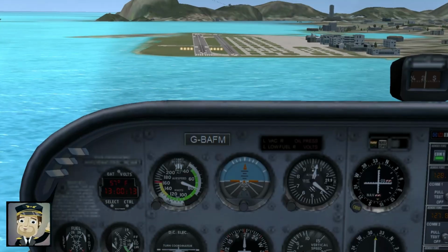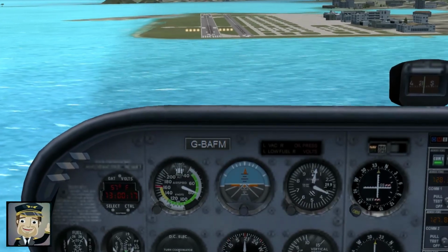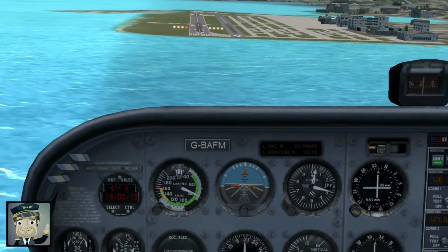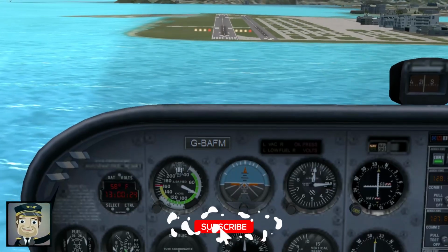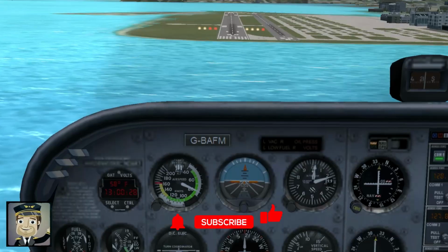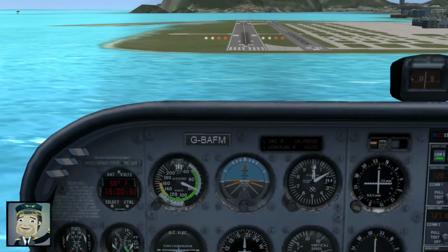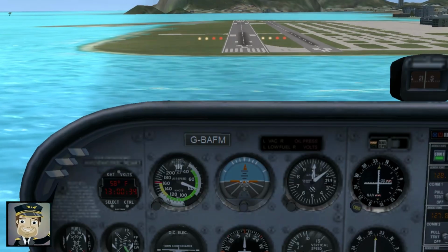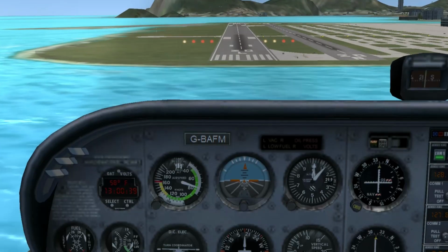During final approach, the pilot's focus narrows dramatically. The outside world becomes secondary. All attention is on the runway picture, descent rate, and the delicate interplay between pitch and power. If anything looks unstable, speed fluctuating, nose wandering, descent becoming erratic, the safest decision is always to go around and re-enter the pattern. Stability is the foundation of every safe landing.